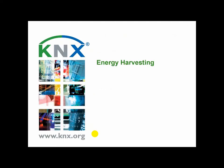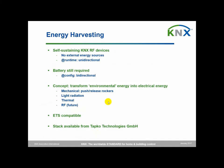Okay, then the actual topic of energy harvesting. Energy harvesting is about self-sustaining KNX RF devices. That means they have no external energy source. These devices are at runtime unidirectional. That means they can only send information, they cannot receive telegrams. That means that a battery is still required, specifically in the context of configuration, because during configuration such a device needs to be bidirectional, otherwise it cannot be programmed or configured.